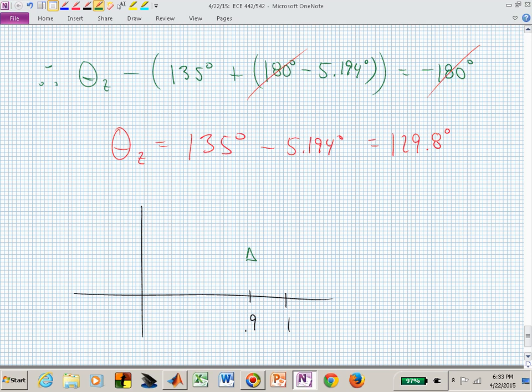It's to the right, isn't it? My zero now of this PI controller is now somewhere there, isn't it? Meaning this angle is the 128 or 129.8. Like I said, I like to work with these angles that are less than 90. Let me call that theta sub z bar.